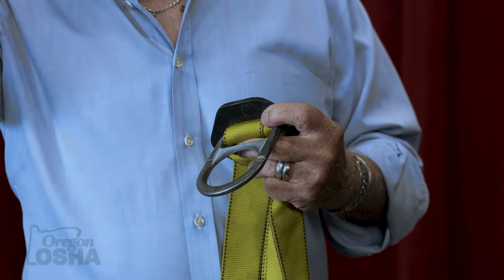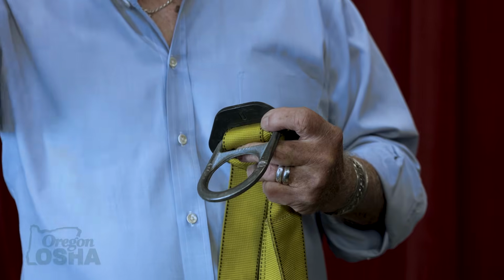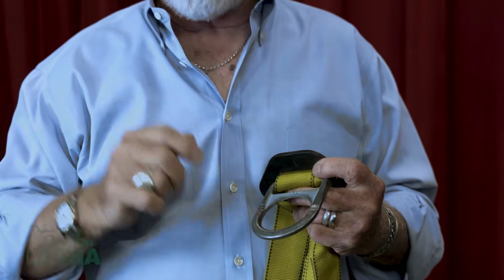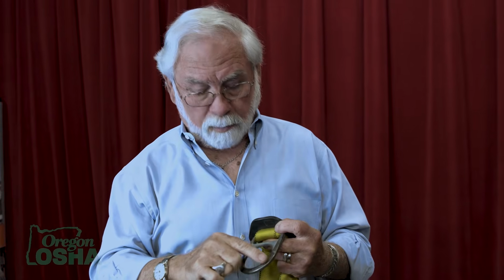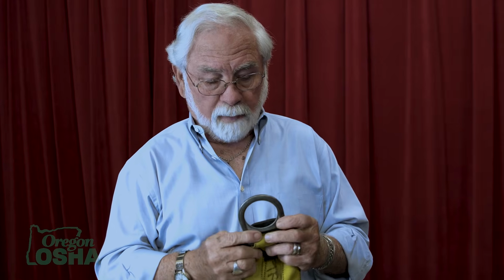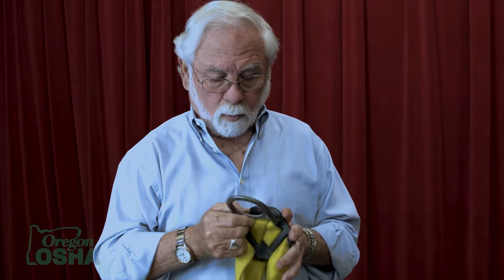So they put apprentices, I'm told, in the towers with grinders behind them to knock off those sharp rods of metal, and occasionally they would come in contact with the D-ring. Never inspected. Do you have the same strength in a D-ring that's new and used and perfect as opposed to one that has been worked on?